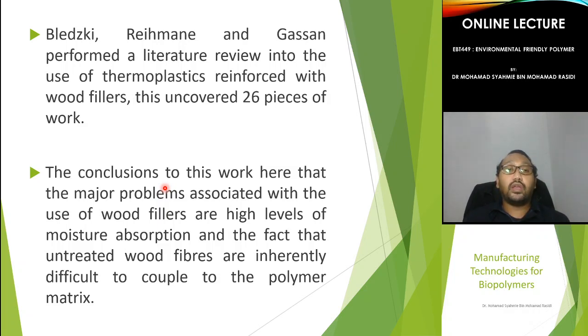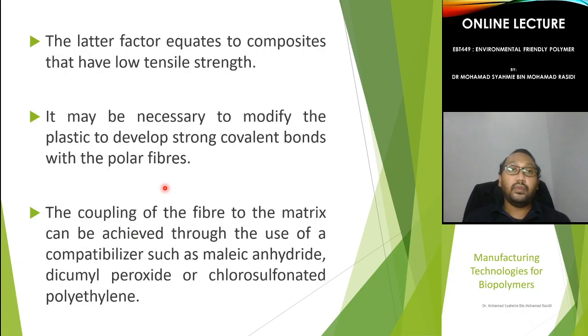Meanwhile, due to this hydroxyl content, commonly there is a polarity issue. When the polarity of the filler and the matrix are different, the homogeneity of the blend cannot be compatible. The latter factor equates to the composite having a low tensile strength. This is due to the different polarity between the filler and the matrix.